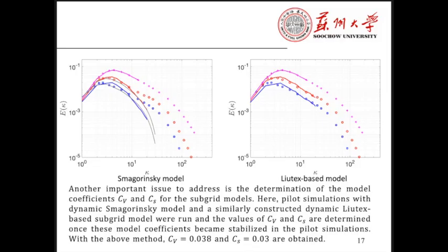We can see that the results of the subgrid model resemble the filtered energy spectra in physical space, while the vortex-based model matches the experimental spectra, which indicates that the vortex-based model has properties resembling a low-pass filter in the spectral space.